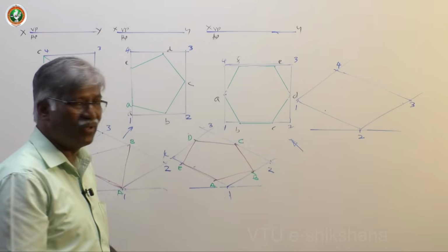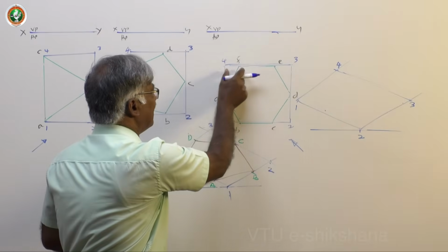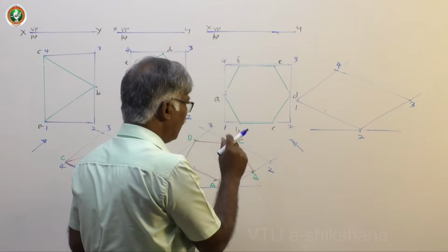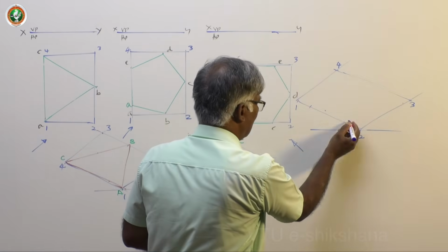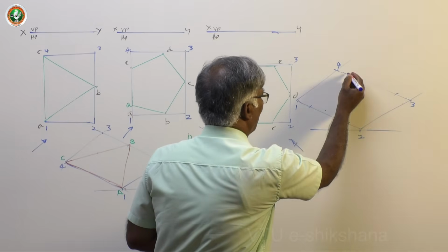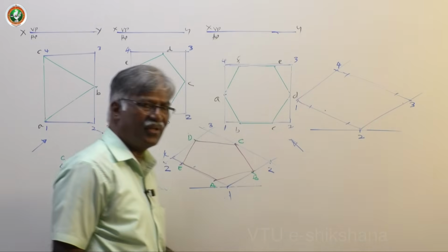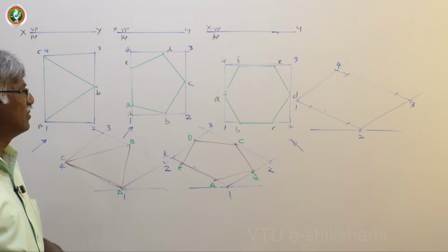It's very easy to identify. 1B equal to C2, that is also equal to E3, F4. So manually how to work? You take between 1, 2, same compass, use the same distance you use with the compass and draw. In computer you fix these 2 and then draw parallels. Automatically you will get it, or use any other strategy to place the points suitably.